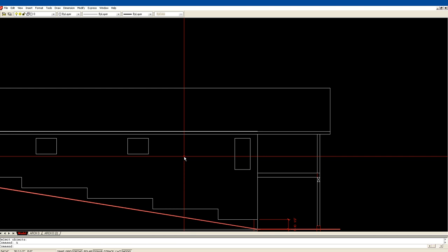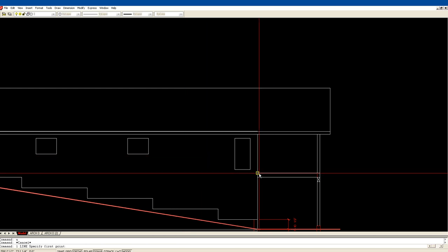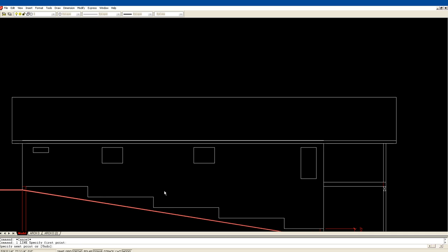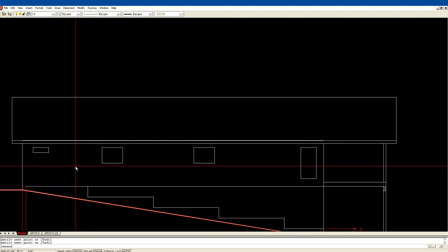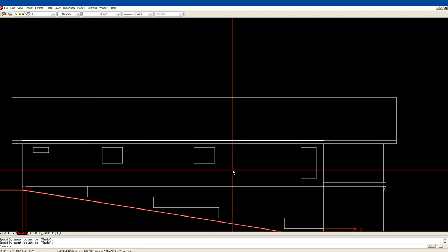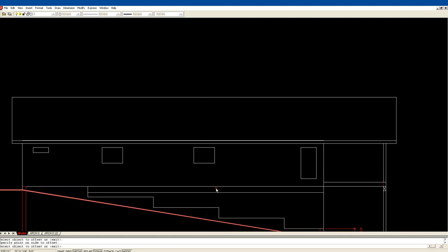Actually, we do. Let's put it back in. Well, let's do it from the bottom because we're going to do the basement windows now. From the basement windows, same idea. I have a couple of plates, a header, the 2x10 header, and then a plate at the bottom of the header. So we're just going to go 14 inches.